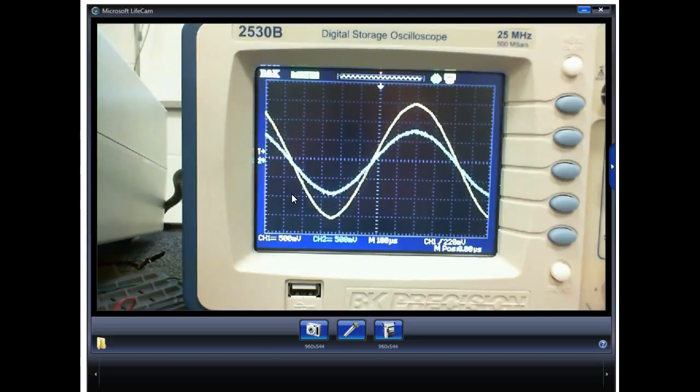Okay, so what am I shooting for? Half. Because if it halves, that means the input resistance of the amplifier has to match the resistance of the pot, right? So we got 3 volts, so we're going to try to get it down to about 1.5 volts.